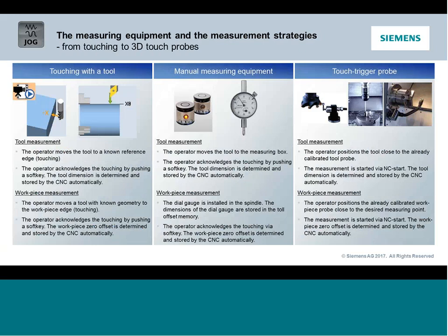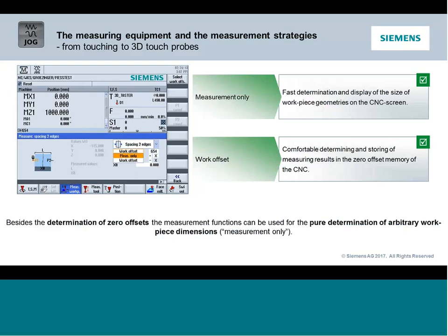Now, auto is a different story. You obviously have to have a probe because it's all automatic processing. But if you need to set an edge, just check an orientation, maybe tip an angle because you're offsetting a skewed vise, and you don't have a part probe, you can still use the cycles that are available in jog in the Siemens Sinumerik controls.